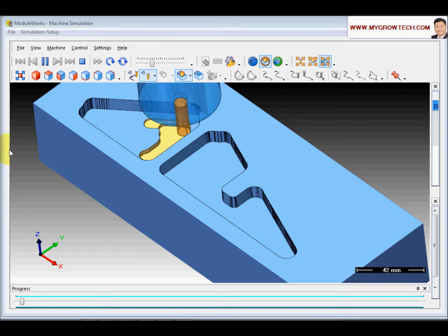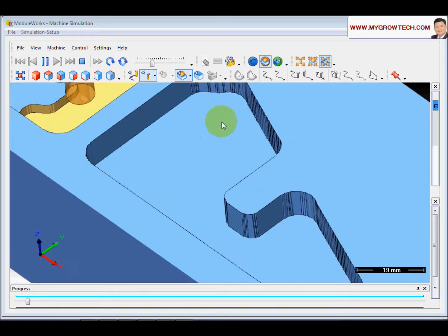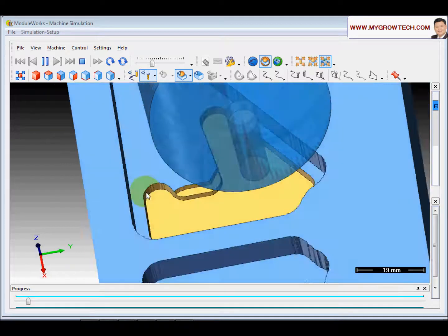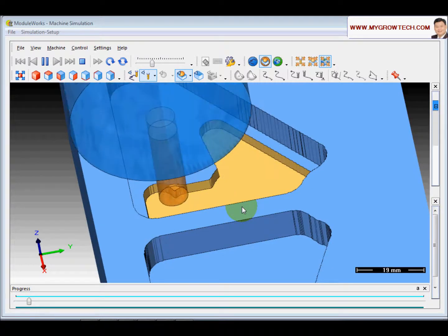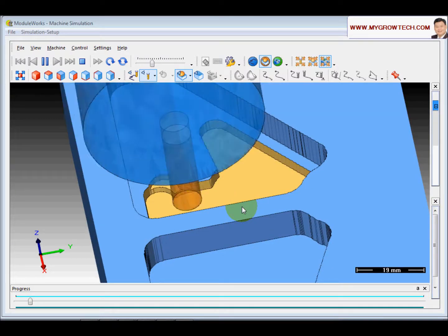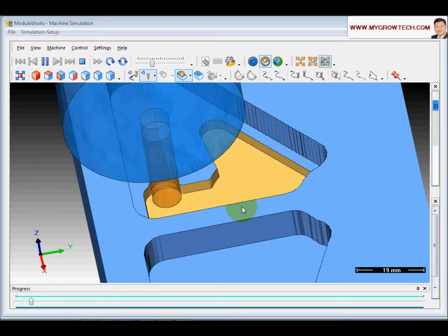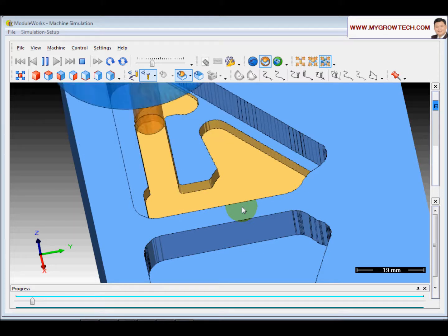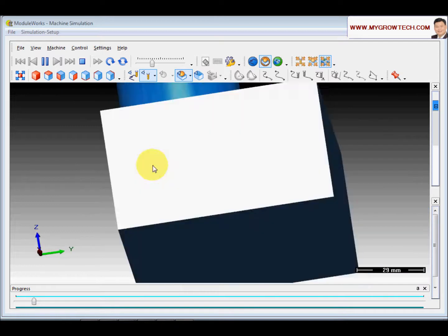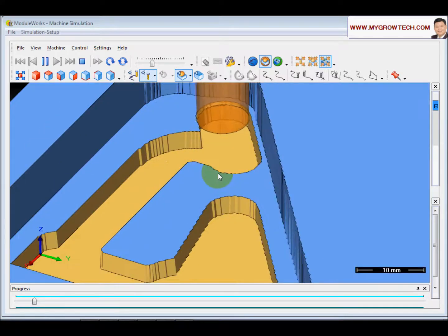My actual down step that I set is 3 mm, but now you can see some areas are creating less than 1 mm down step to cut. This is called create down step. So you can control the maximum number of down steps the system can divide the load into. So with this create down step option, the load is also reduced.